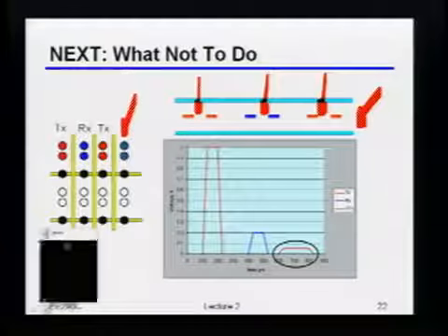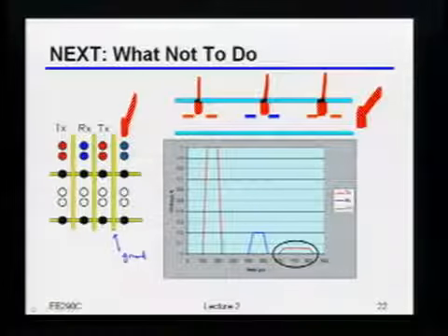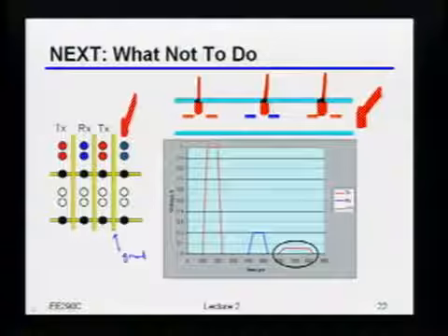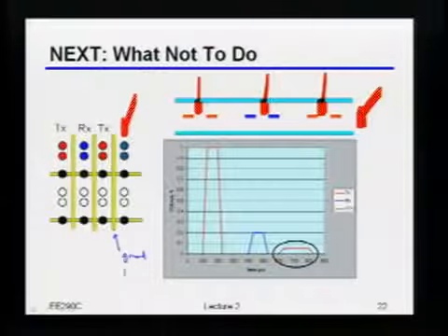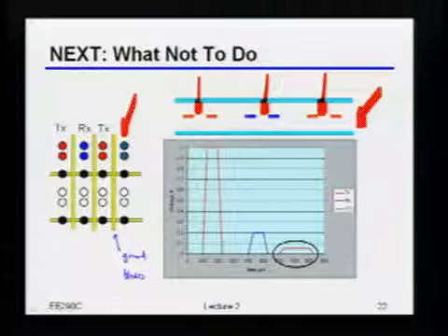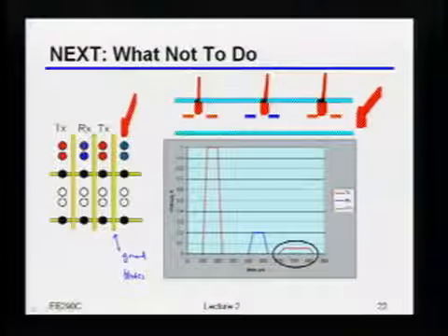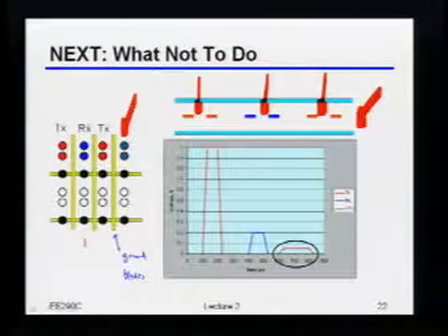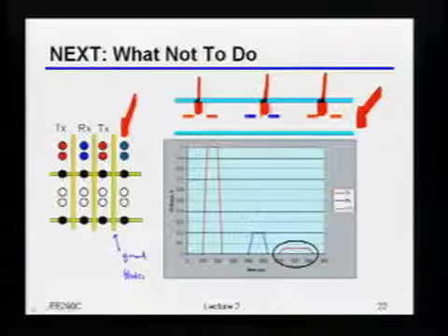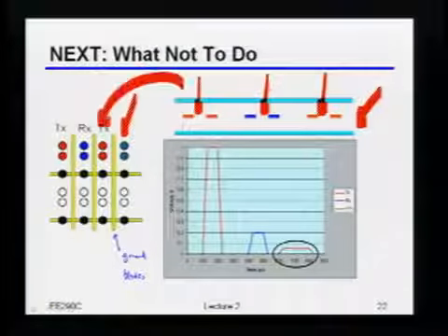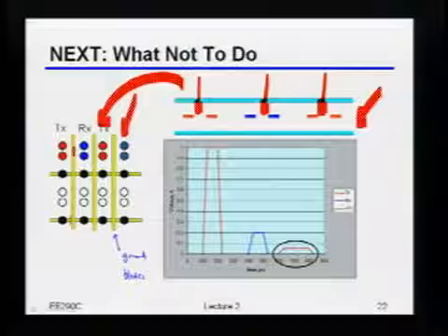By the way, these little gold things over here are essentially ground lines. That's obviously to try and make life a little bit better. These are sometimes called ground blades in the context of connectors. Nonetheless, if I do some arrangement like this, remember this is a vertical picture here. If I'm taking this thing and plugging it into that, I may not actually have these ground lines going up vertically. I've only got them in this transition region here.